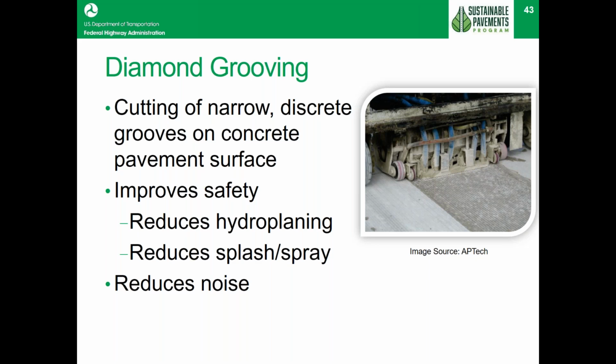It helps drain the water out. This is not always done in the direction of traffic. Sometimes they'll do it transversely across the roadway, and give some grooves in there that'll help with friction and help deal with safety problems that do occur in pavements.